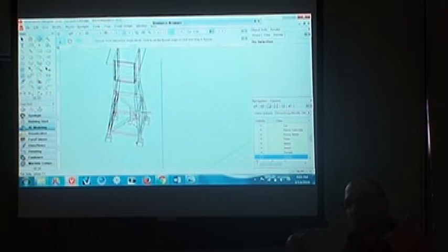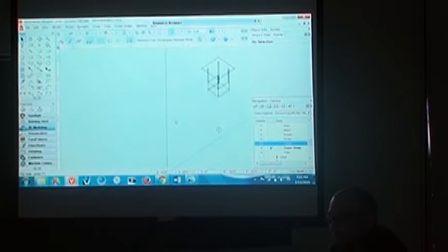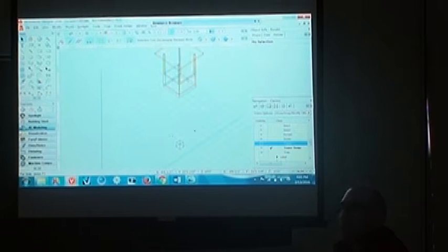How can we extrude something like that? That has to follow this diagonal path from down out here to in up here. Like how can we do that? Well, this is a situation where a custom working plane is very handy. So here I've got the upper part of the tower that I already made using my extrude, wall, window, basic functions, and I've created the footing down here for what I want the leg to sit on.